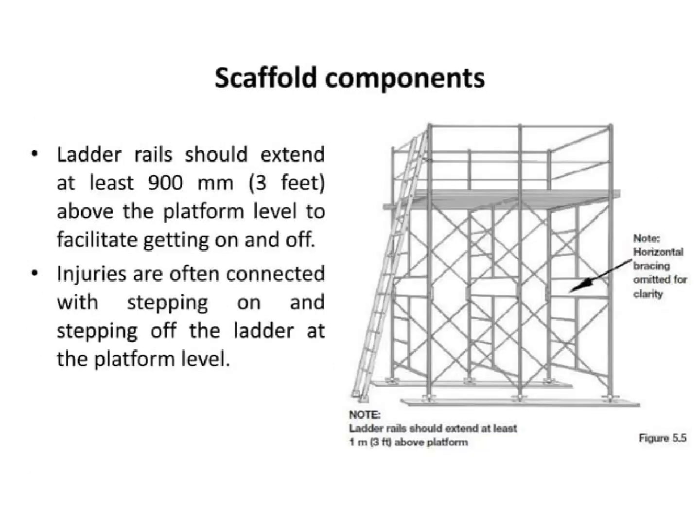Scaffolds should always be used with ladder rails extending at least 900 mm, 3 feet, above the platform level. This is to prevent injuries caused by getting on and off at the platform level. Therefore, it is important to adhere to the safety measures when using scaffolding.